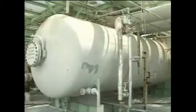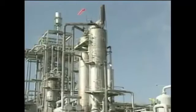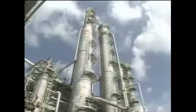One way to separate an azeotropic mixture is to use a solvent. The solvent is a substance that, when combined with the azeotropic mixture, allows the separation of components to take place. Another way to separate an azeotropic mixture is to use two distillation towers in a special arrangement.